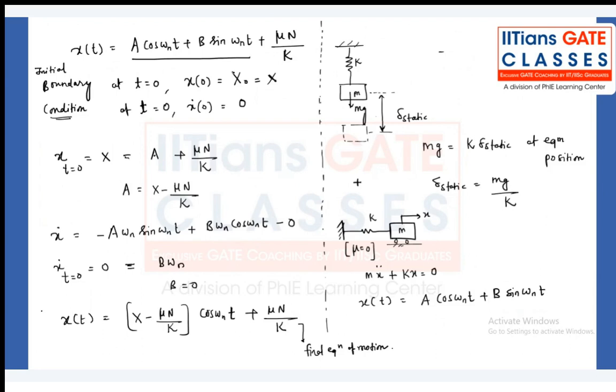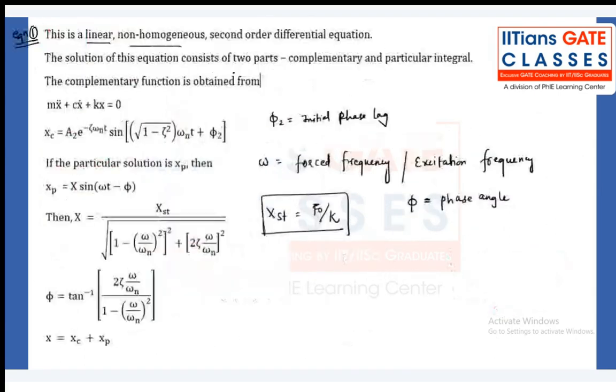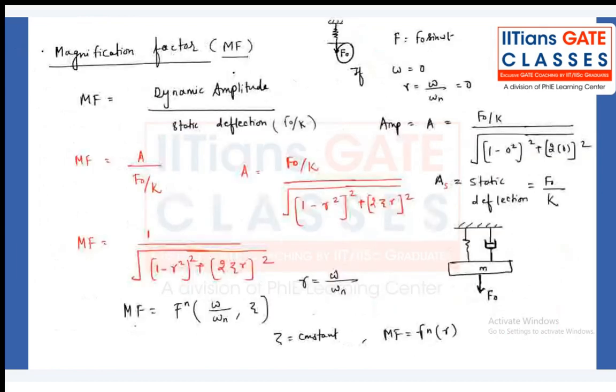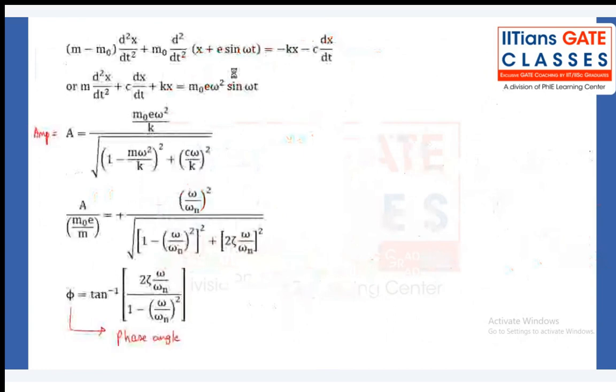So can I say the damped natural frequency is still the value of omega n? But in case of viscous damping, it is replaced by omega d, which is equal to under root of 1 minus zeta square into omega n. Are you getting my point? So that's why I have written here omega d for case number 2 still remains the same, omega n.